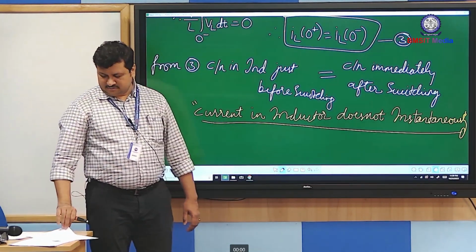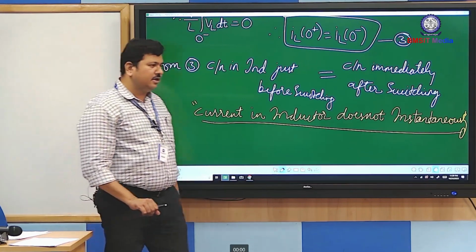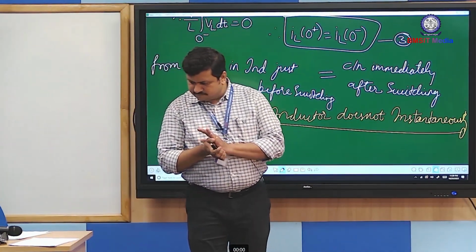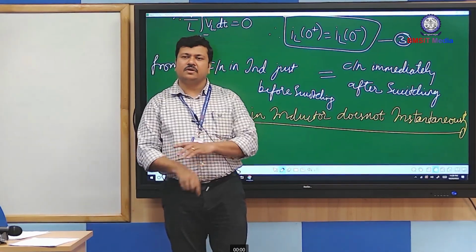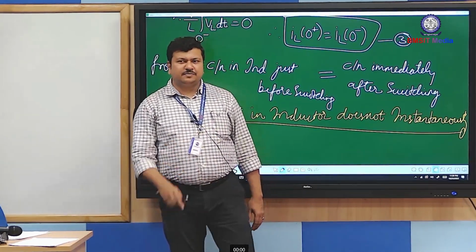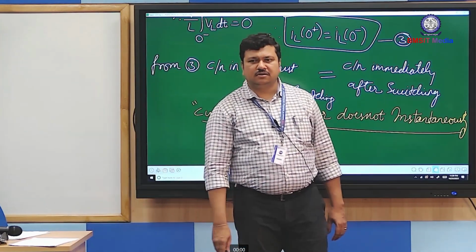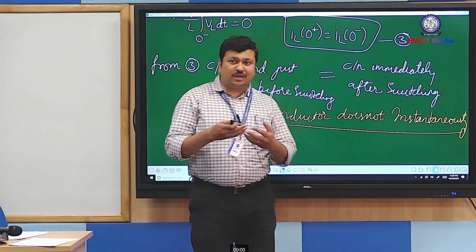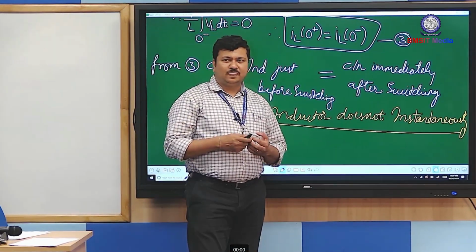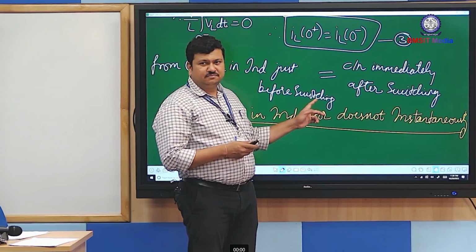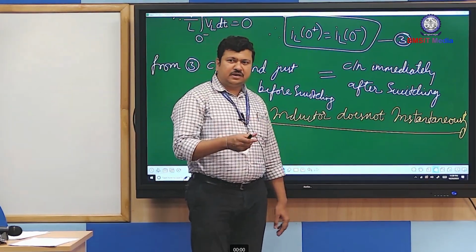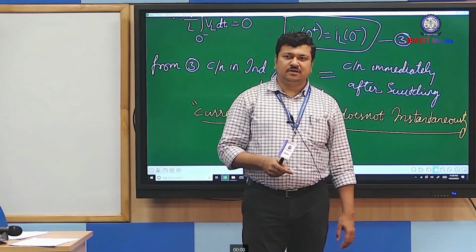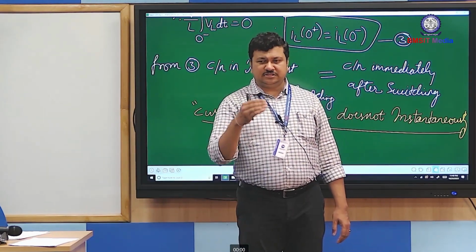Now go back to the inductor analysis with AC circuits that we have already studied. What did you conclude there? That current lags behind the voltage, right? Why does current have to lag behind voltage? The reason is here. By the nature of inductance, the inductor current will not change instantaneously. The voltage applied to the inductor will change instantaneously.